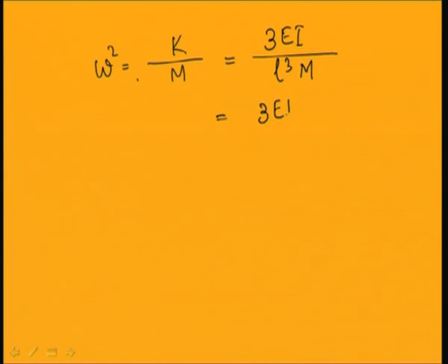The frequency is the root over k by m, so this becomes root over 3 E I by m L cube.